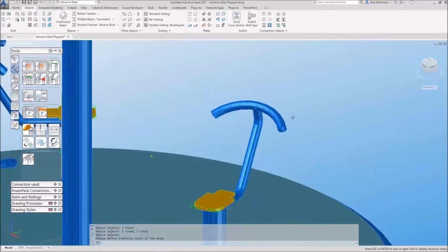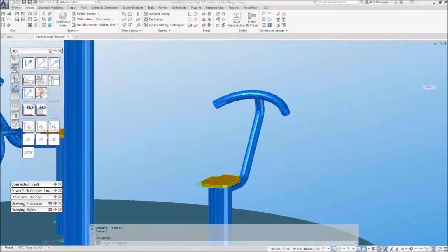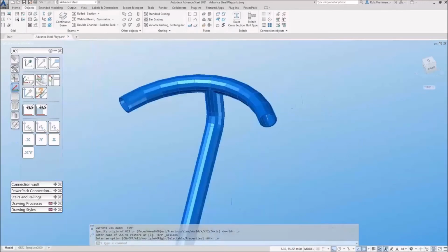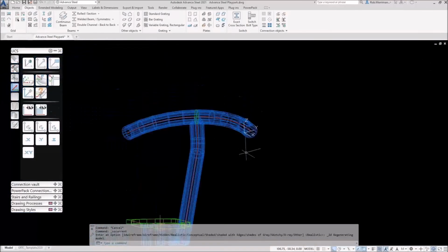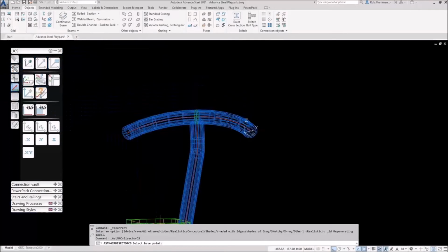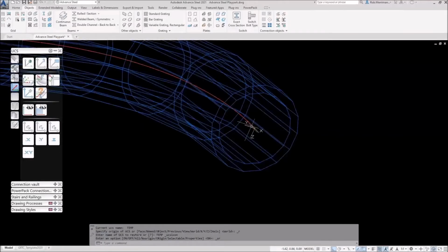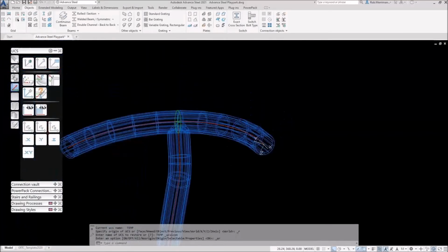Now for these bang-in end caps, I should have probably put them in beforehand. I need to get my UCS on the end of this tube. So what we're going to use, in our UCS tab, there is a command, UCS at curved beam. So we'll choose a curved beam, hit enter. Oh, maybe I need to be in the 2D wireframe. That's now put my UCS. I needed to do the second point. That's now put my UCS on the end there.